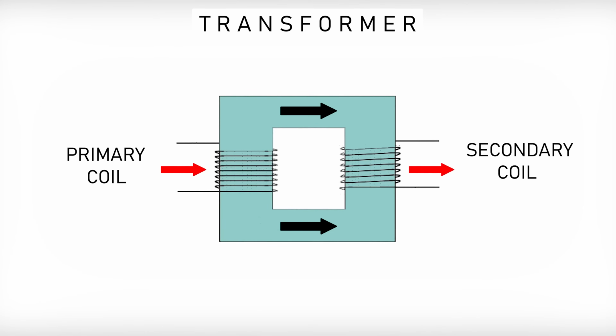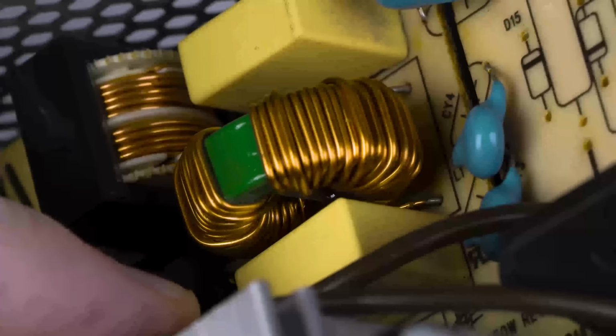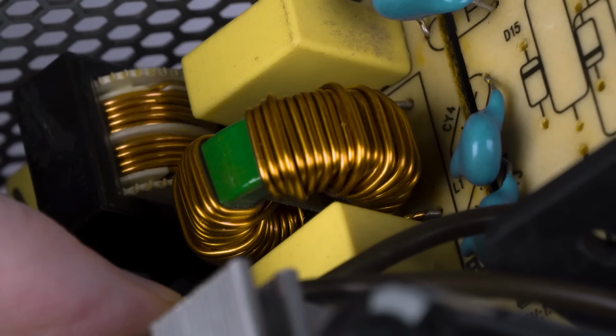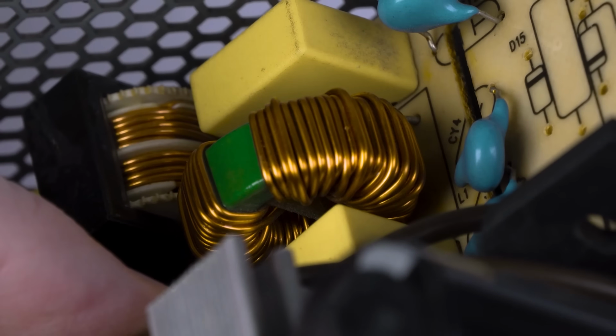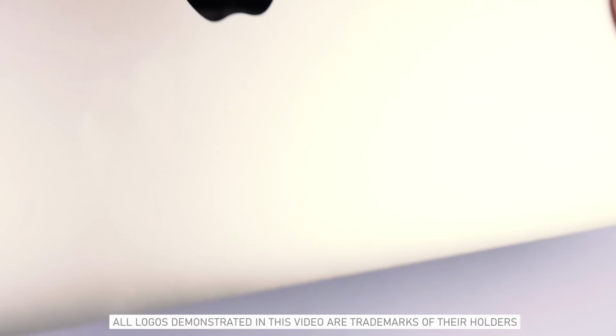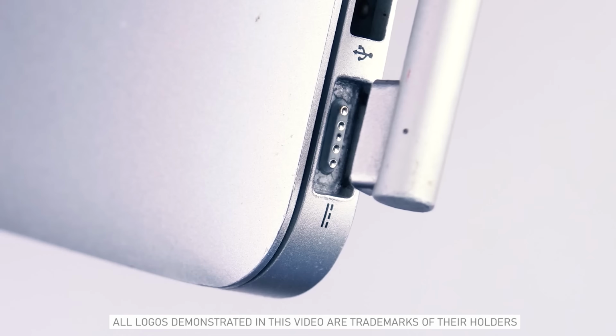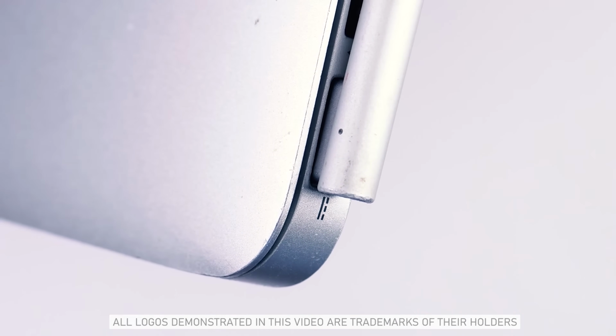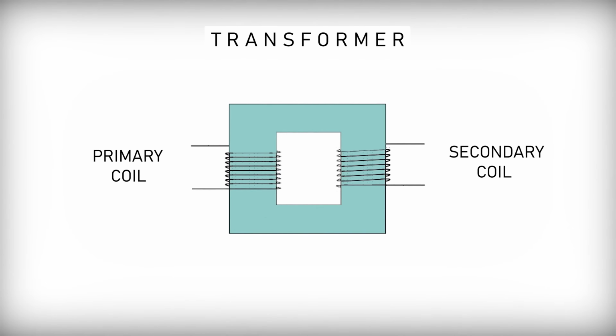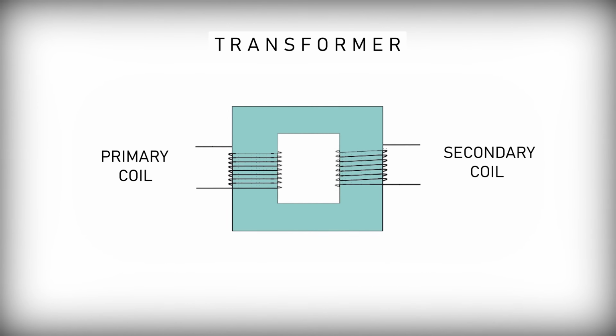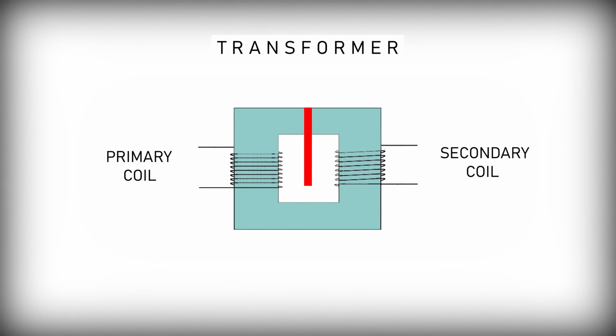In general, it is possible to step down voltage in different ways, and strictly speaking, a transformer is not necessary to achieve this. But the main reason why transformers are used almost everywhere is user safety considerations. Any electronic device that assumes interaction with a human is not allowed to have a direct electrical connection to the wall outlet. As the transformer's windings are isolated by design, it can provide the so-called galvanic isolation, that is, isolation of output circuits from the input circuits.